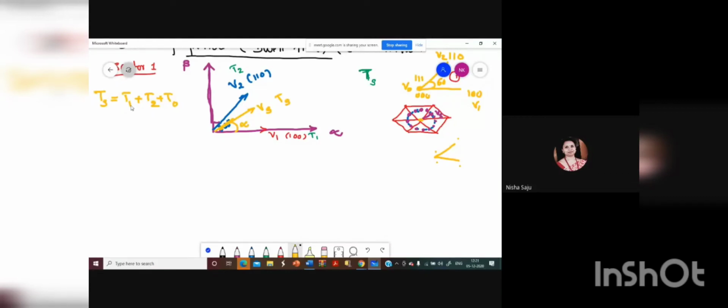For that, you have to take the volt second balancing. So what do you mean by volt second balancing? Volt second balancing means we are having V alpha and V beta here also, right? As the axes, you are having V1, V2, Vs and the zero vectors. So you have to take the horizontal component along this alpha axis. You have to consider the vertical component also.